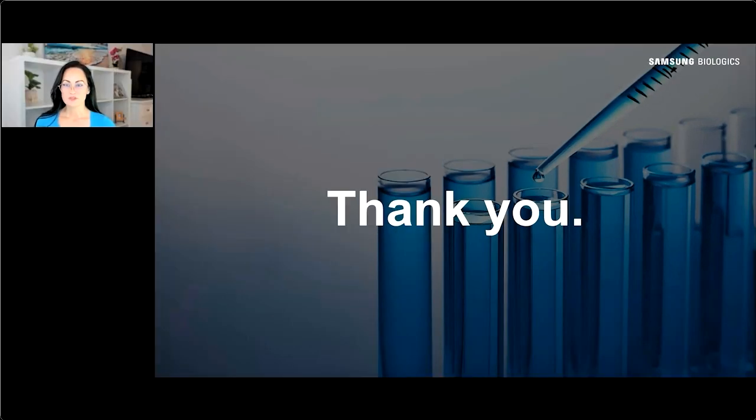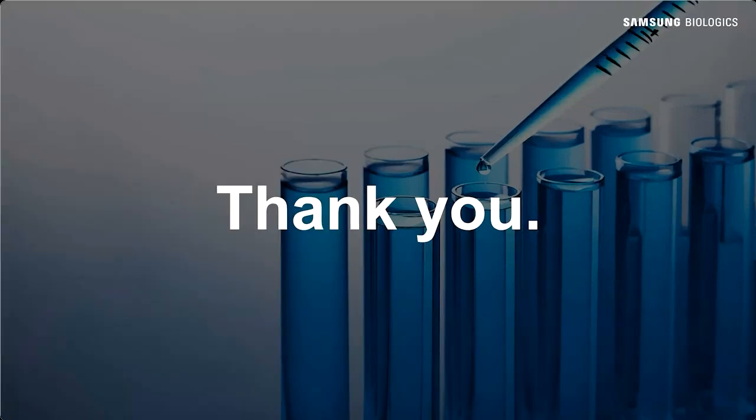All right, first question. How do you evaluate if a facility and its equipment are fully compatible with the process requirements? Assessing facility fit is critical, and the capability to manufacture the product needs to be determined through gap assessment. Based on the process data provided from the sending unit, mass balance is generated.